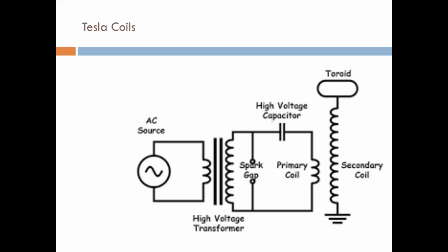It is possible to give either an AC or a DC supply to the primary winding, to the capacitor C, through the spark gap. Suppose the spark gap is triggered at a desired voltage V1. The voltage coming from the high voltage transformer is triggered, which induces a high self-excitation in the secondary. High excitation is produced in the secondary.